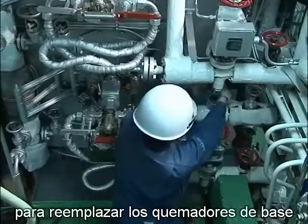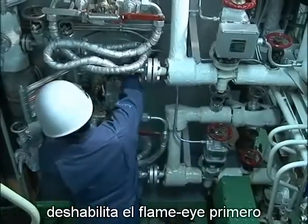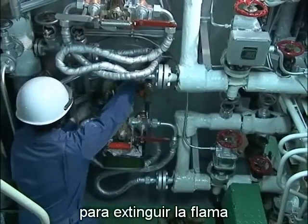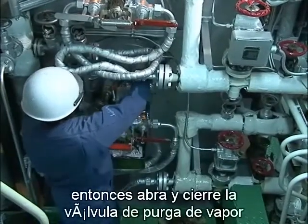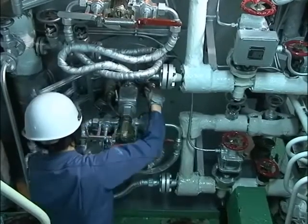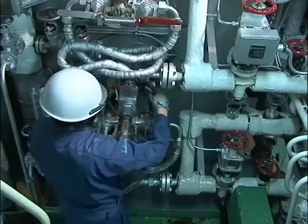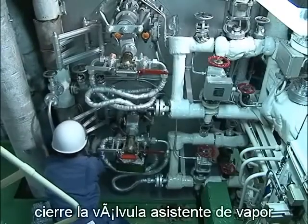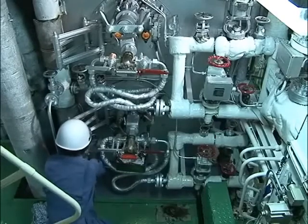To replace base burners, disable the flame eye first and close the fuel oil inlet valve to extinguish the flame. Then open-close the purge steam valve to purge fuel oil remaining in the burner. After fuel oil purging, close the steam assist valve securely.